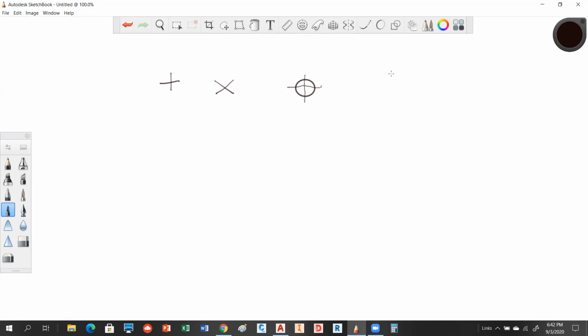There are two variables that govern how these look. One is called your PDMODE setting, and the PDMODE setting is the setting that makes it look like that, or like that, or like that. The PDSIZE setting determines how big your point is. And so if we have a PDSIZE of, let's say, 1/2 inch, that would be that setting.